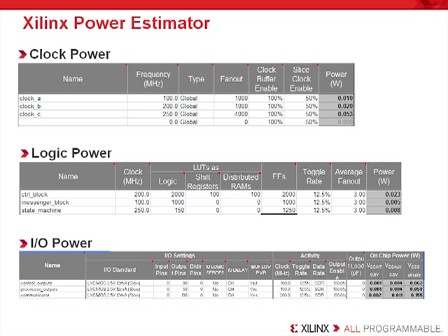The I/O power requires the same kind of information, except it also needs your output loading and some details about how each IOB will be configured. That is, what I/O standard is used, whether the output enable is used, data rate, SerDes functionality, I/O delay, and of course slew rate. As you will see, I/O power consumption is a considerable factor in your overall system power consumption.